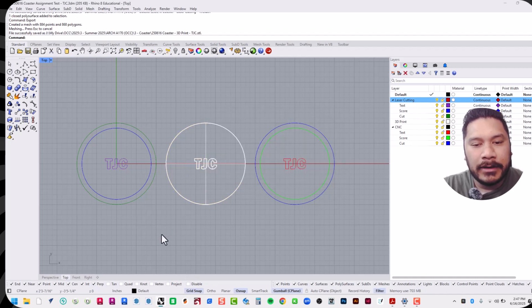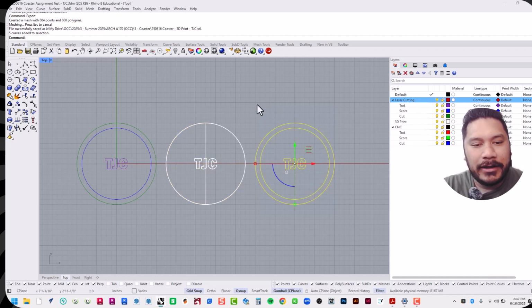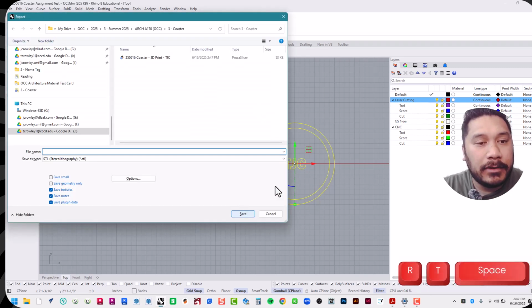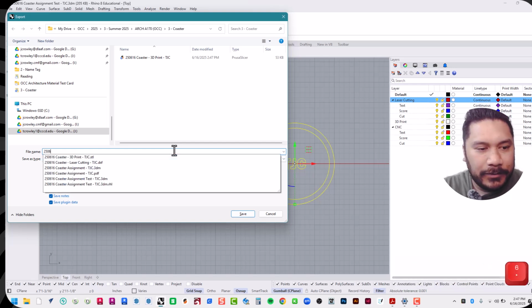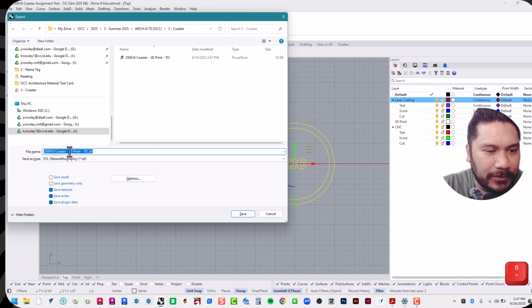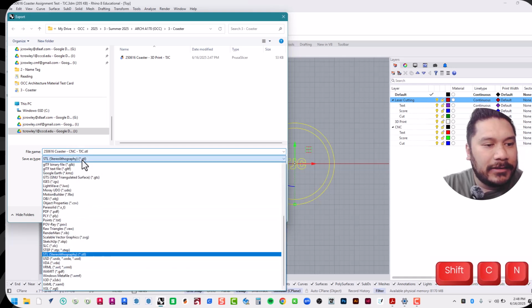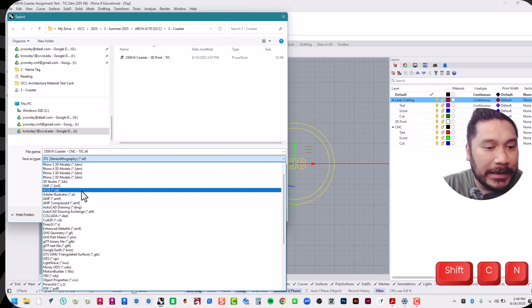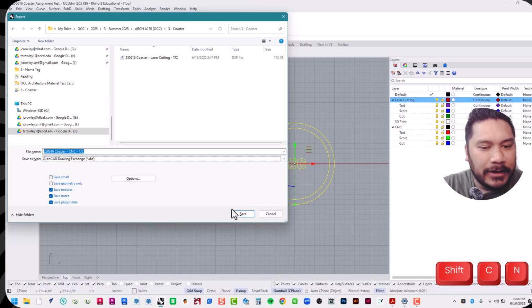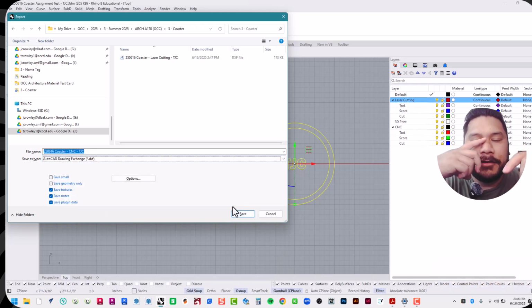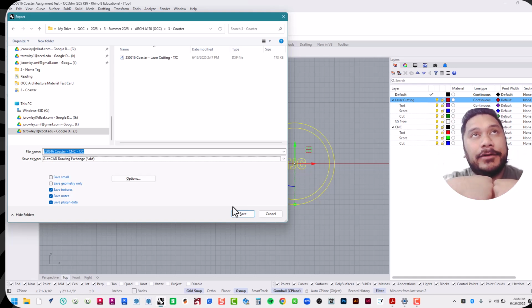Okay, and instead of an STL, once again, I'm going to want a DXF. I prefer DXF files over SVG files. So scalable vector graphics versus AutoCAD Drawing Exchange, both work, but I've learned over the years that an SVG is a scalable vector graphic, and therefore when you import your SVG into any program, it will come in various sizes. Okay, because it's just its nature, it's in its name, scalable vector graphic. That's the advantage of using something like that.